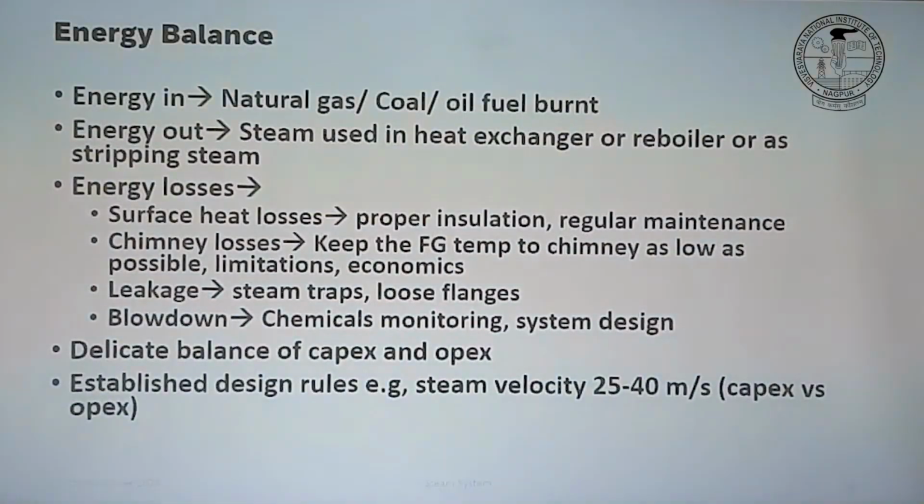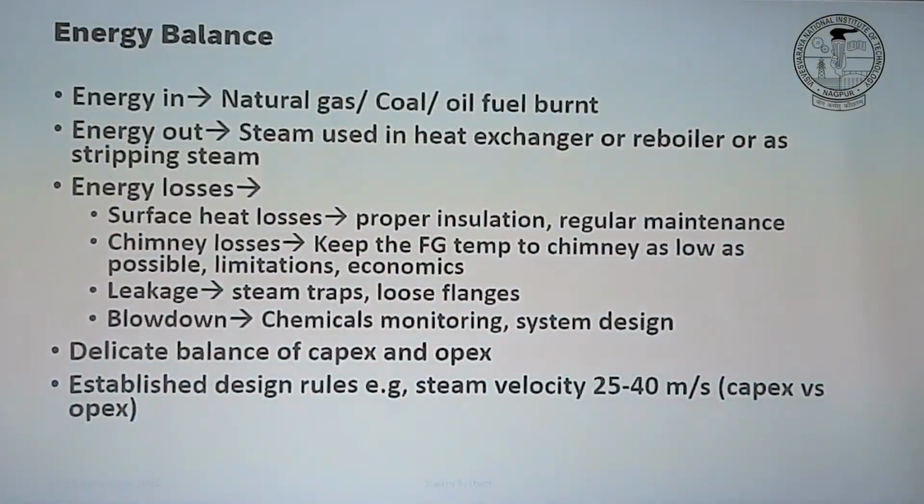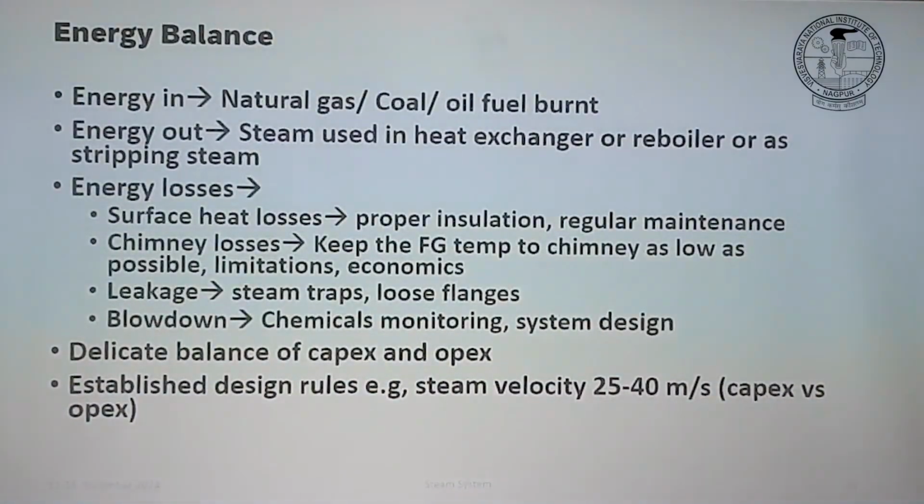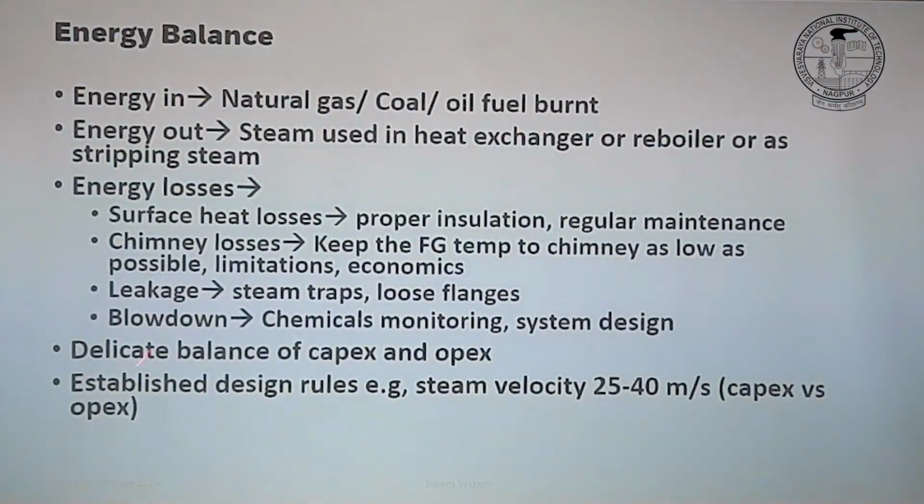Water as such is not corrosive, right? But water mixed with carbon dioxide or some other dissolved gases is highly corrosive. So in such systems, you need to put some chemicals in to inhibit corrosion issues, right? Since you put in external components, if you do not take them out, they will start accumulating within the system, right? So you have to do blowdown to avoid accumulation of these chemicals. So that's also a source of energy loss.